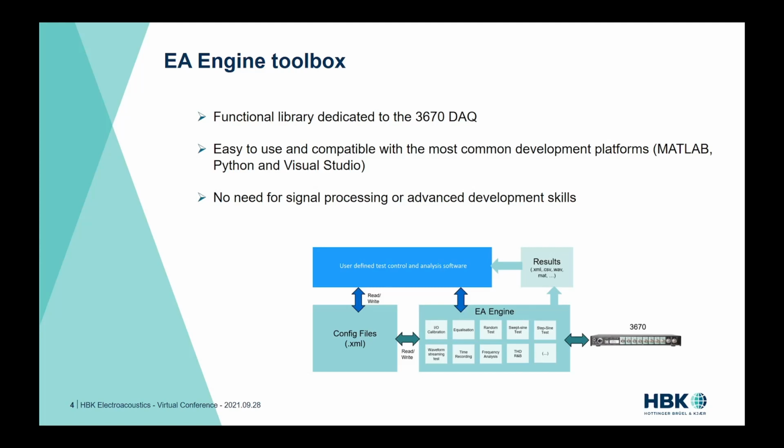You can do I/O calibration, equalization, random, sweep sine, step sine, and waveform streaming tests. You can do time data recording. All the functionalities that are mandatory to do frequency analysis or distortion, like THD or Rub & Buzz calculation, for example, are already included in it.